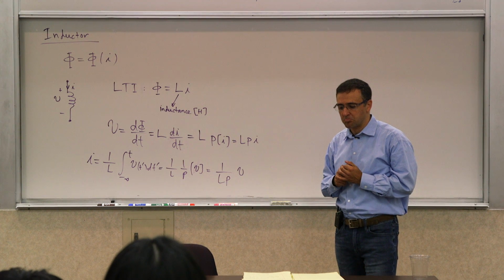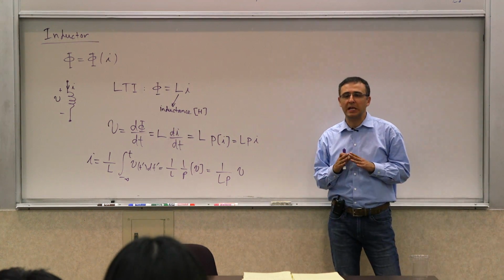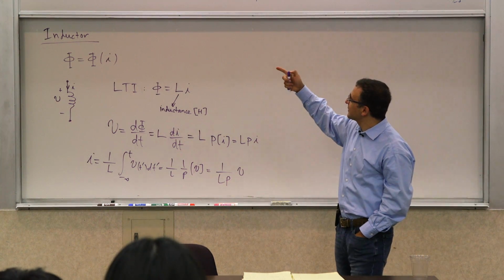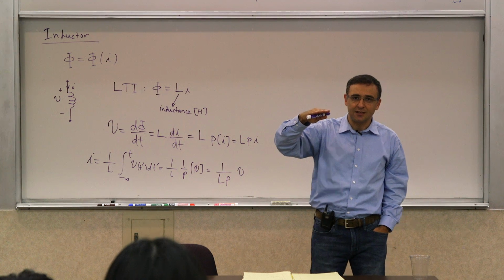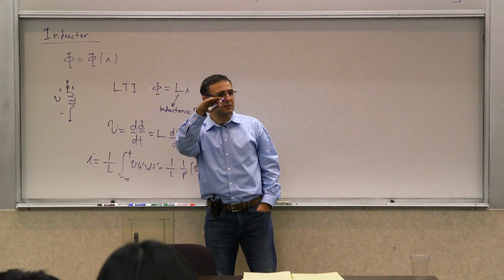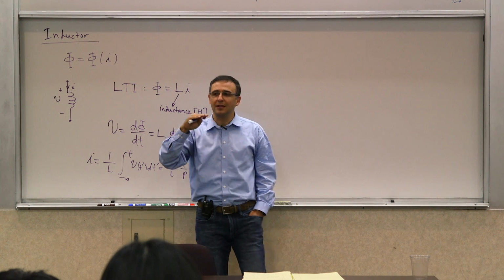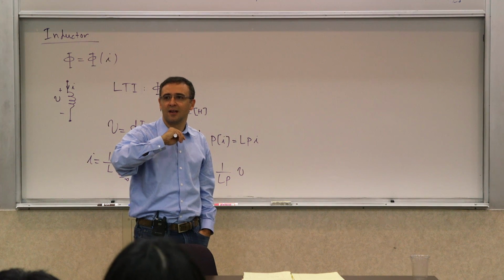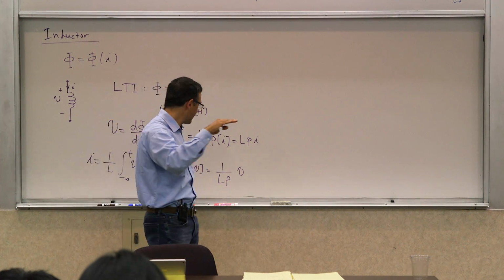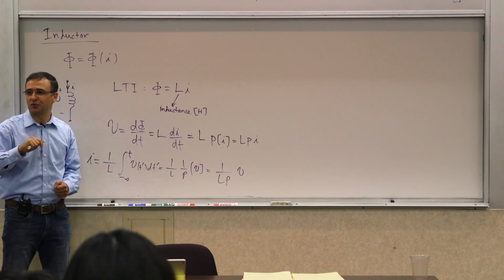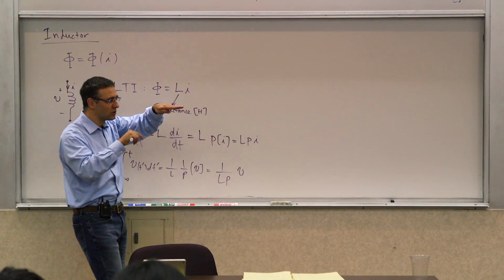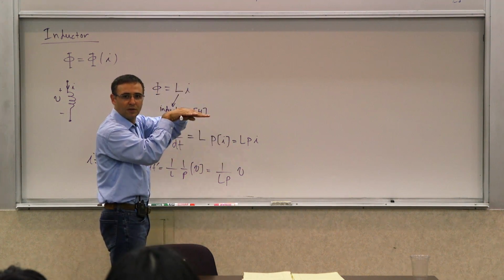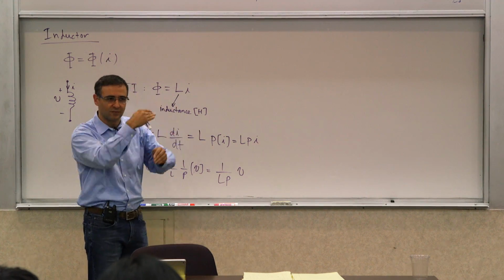Okay? So those are basic components, really elementary components. Now, if you think about it, at the end of the day, these things basically take it one level higher, right? Resistor current depends on its voltage. If you look at the capacitor current, it depends on the derivative of the voltage. If you look at the inductor current, it depends on the integral of the voltage. So you have one component whose current depends on the voltage, one whose current depends on the derivative, and one whose current depends on the integral, levels up and down.